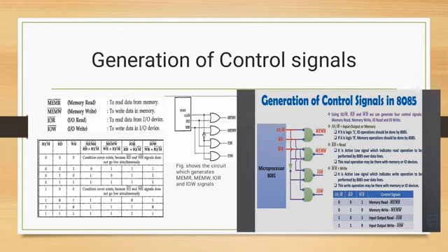So for the control signals I have written over there, for the memory related operation, the read pin is 0, which is also an active low pin. So the entire operation is MEMR, that means a memory read operation is performed by the processor. The write pin is 1, and since it is an active low pin, applying 1 means it is not activated.